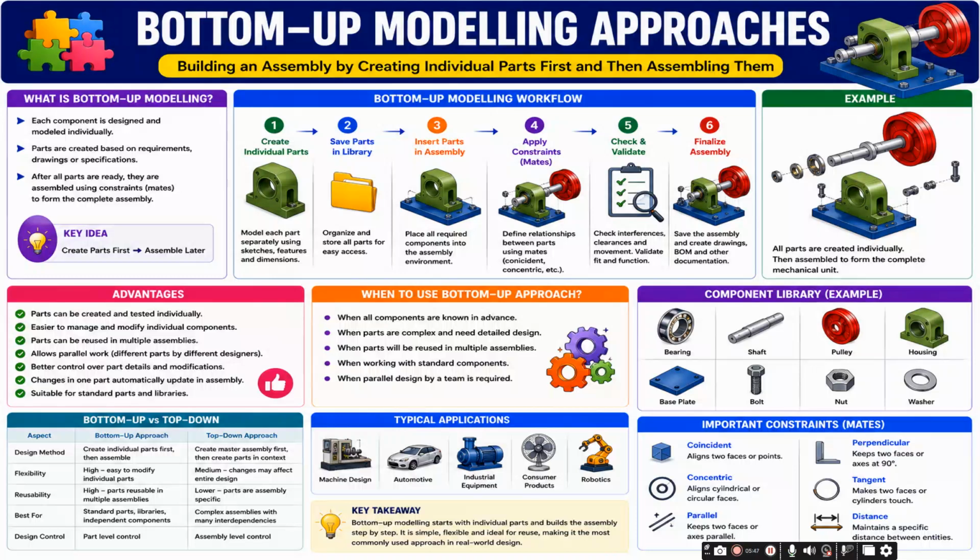When to use the bottom-up approach: when all the components are known in advance, when the parts are complex and need detailed design, when a part will be reused in multiple assemblies, when working with standard company components, and when parallel design by a team is required.